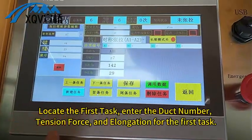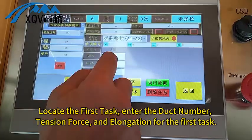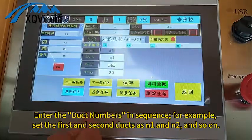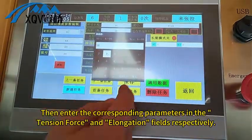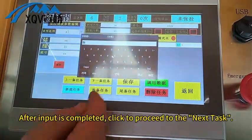Locate the first task, enter the duct number, tension force, and elongation for the first task. Enter the duct numbers in sequence. For example, set the first and second ducts as N1 and N2, and so on. Then enter the corresponding parameters in the tension force and elongation fields respectively. After input is completed, click to proceed to the next task.